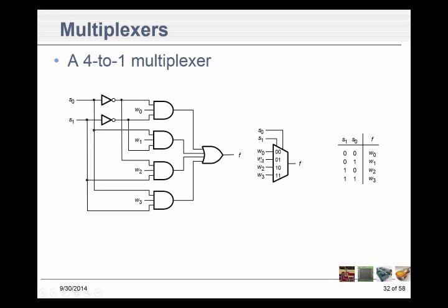So that means I could hook up a 0 to this or ground it, a 0 to this or ground it, a 0 to this or ground it, and a 1 here, tie it high, and these would be like the two inputs to an AND gate. Because when I said 0 here, this 0 on this input goes to the output. When I've got a 1 here, this 0 on 1 goes to the output. When I've got a 2 here, that 0 on 2 goes to the output. When I have a 3 here, the high voltage goes to the output. So we can make this a truth table for just about anything we want.